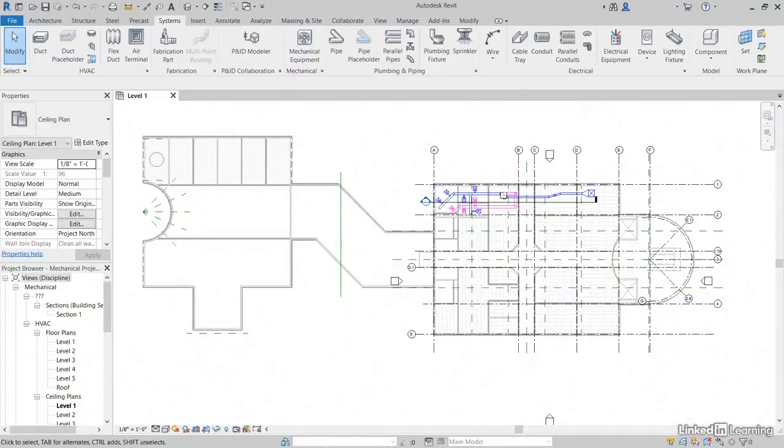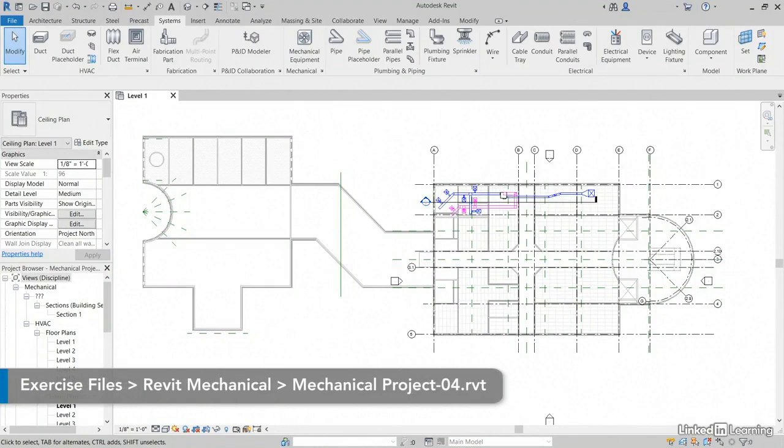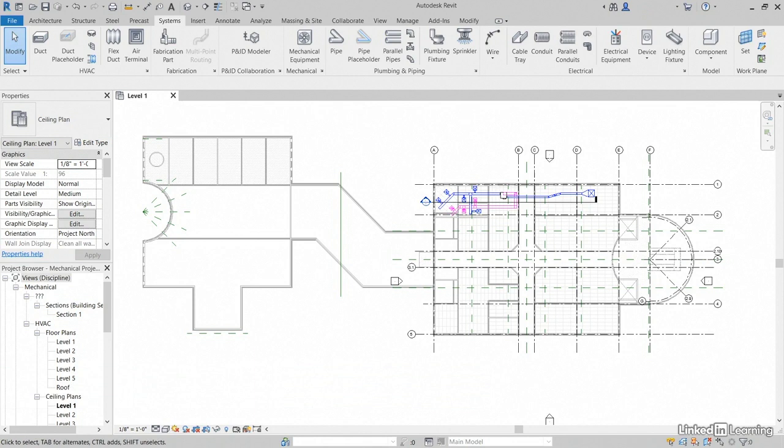So, there's certainly no shortage of items that we need to place into the ductwork. For example, fire dampers, balancing dampers, and end caps just scratch the surface. It's important that we place everything we need into the duct. That way we can depend on the output from Revit reporting on how much airflow is going through that duct.